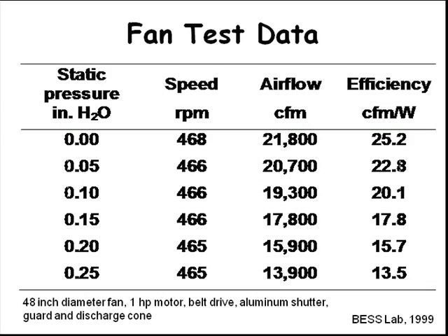I also want to again hit this business about the fan testing data and fan performance here. This is similar data that Larry showed for a 24-inch. This one is for a 48-inch diameter fan. And as you can see here for the different static pressures, the speed, the RPM, doesn't change very much, but the airflow rate, again, decreases as that static pressure goes up and the efficiency goes down.